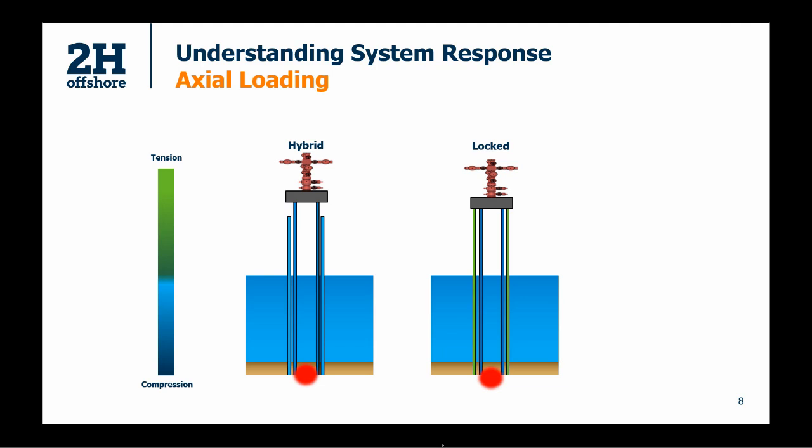So these two systems looked almost identical during drilling, but you can see once you go into production that you're looking at two very different axial stress states in your conductor and your surface casing. So it's very important to understand what wellhead system you have and what that's doing to the axial loads in your system.